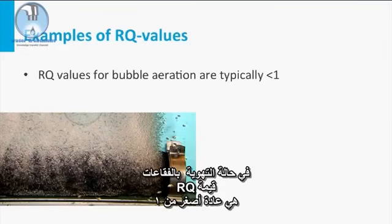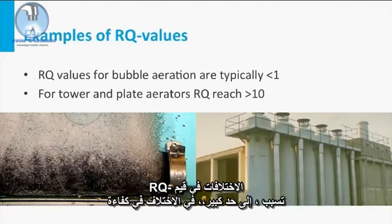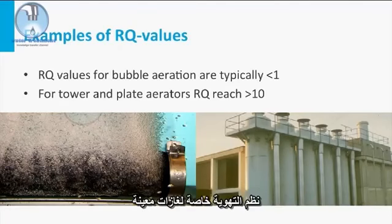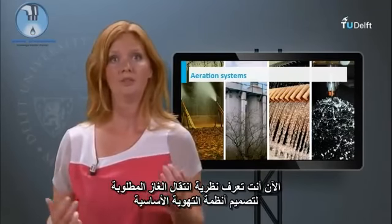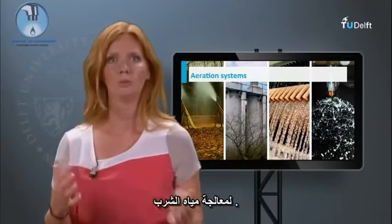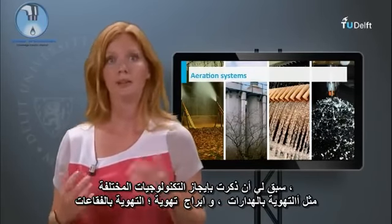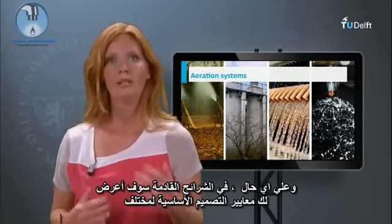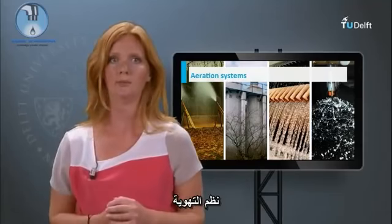In the case of bubble aeration, the RQ value is typically smaller than 1, and in the case of tower aerators and plate aerators, RQ values of 10 and higher are applied. The difference in RQ values cause, to a great extent, the differences in efficiency of these systems for specific gases. Now you know the theory of gas transfer that is needed to design basic aeration systems for drinking water treatment. I've already briefly mentioned different technologies, such as cascades, tower and bubble aeration. However, in the upcoming sheets I will introduce you to the key design criteria for different aeration systems.